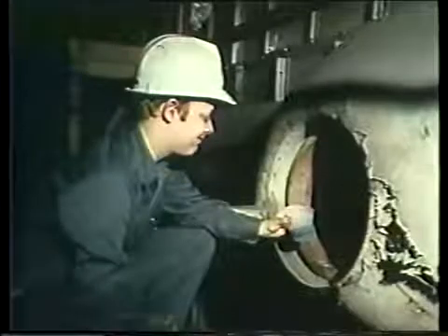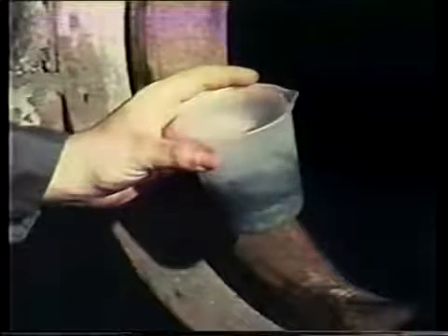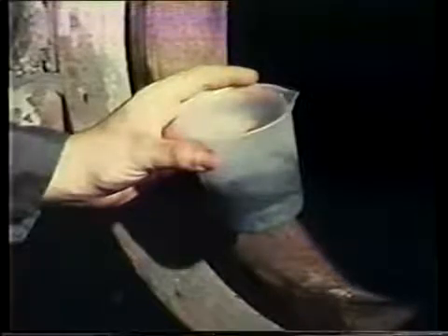Sludge is a product of impurities in the boiler water. Sometimes impurities enter the boiler with a feed water. Feed water is water pumped into the boiler to be heated. Other impurities adding to sludge are corrosion products and eroded material. In some cases, feed water treatment chemicals can also add to sludge. If you find sludge during inspection, take a sample. Later, the sample should be analyzed to determine its makeup and to help locate other boiler problems.